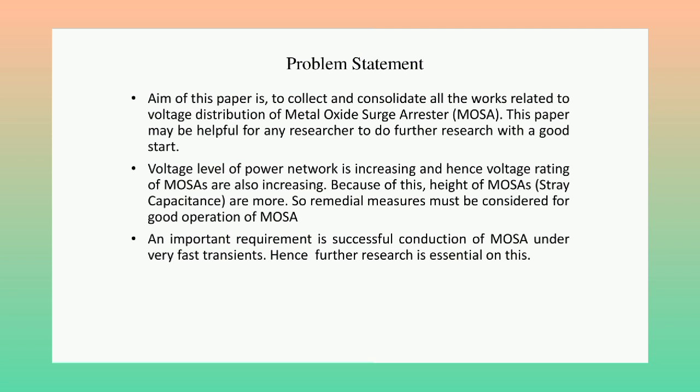The voltage level of the power network is increasing, and hence the voltage rating of MOSAs (metal oxide surge arrestors) is also increasing. Because of this, the height of MOSAs and hence stray capacitance are more. So remedial measures must be considered for good operation of the MOSA. An important requirement is successful conduction of the MOSA under very fast transients. Hence further research is essential on this.